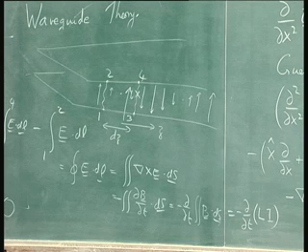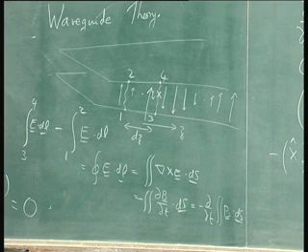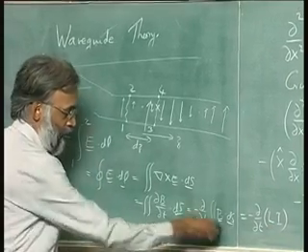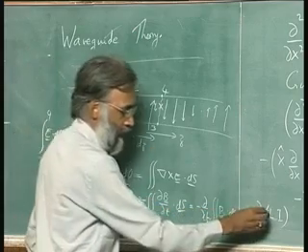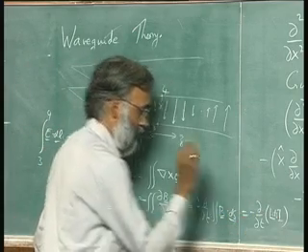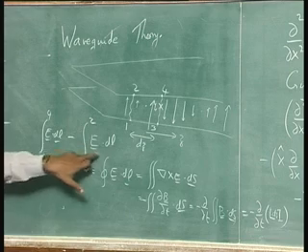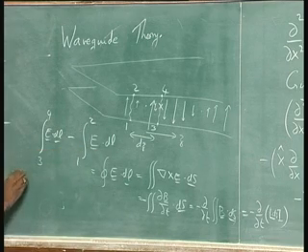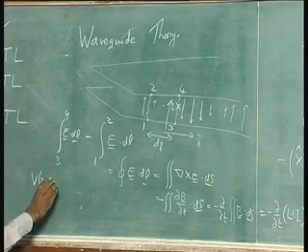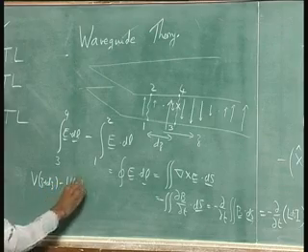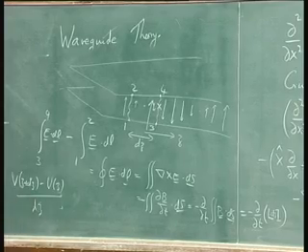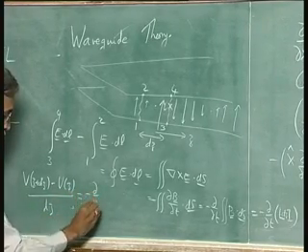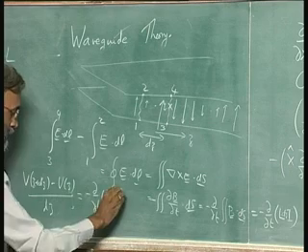Now let us see what we have written. This L, or this flux, is the flux of a region which is dz wide. So this inductance is L dz, and this difference is voltage at Z plus dz minus voltage at Z, and I am going to take that dz out and bring it this side. Divided by dz is equal to minus del T of Li.